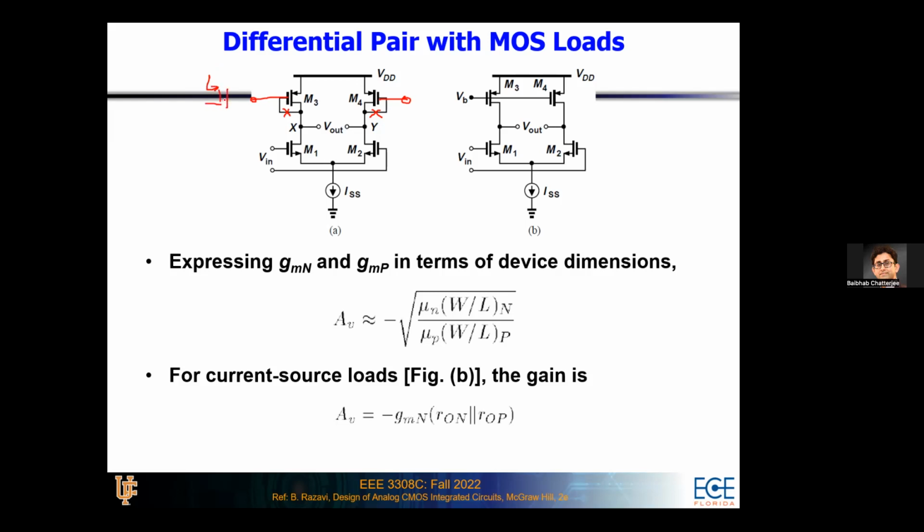So you can have this type of a circuit connected on the left side over here, that another PMOS is connected here, and you're mirroring a current to that PMOS circuit into the gate of the M3. Okay, so you're mirroring whatever current is going in this branch into this branch. So that's why it is called a current source load. And you have looked into current source load for common source amplifiers already. So again, this is nothing different. It's exactly application of the same ideas for a differential amplifier.